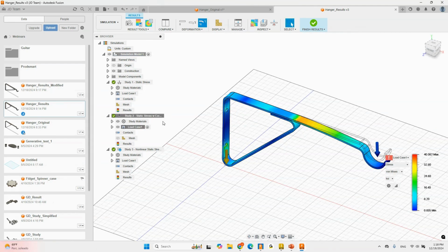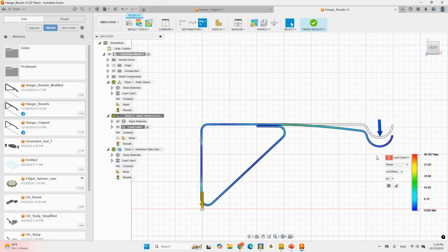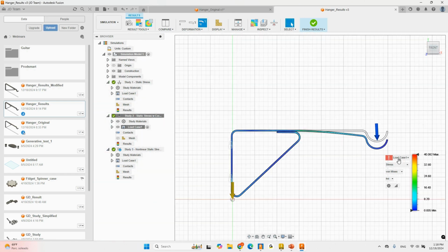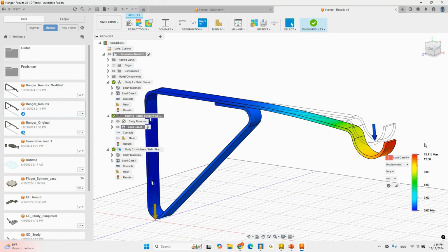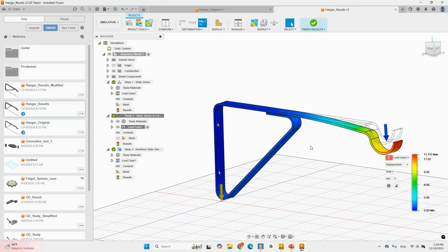Another thing, I can go even a little further down the road and analyze what's going to happen here if I'm getting this type of deformations, right? If I check for displacements, you see that the displacement I'm getting right here, by the end, it's 13 millimeters, right? This is very high for the geometry that I have.